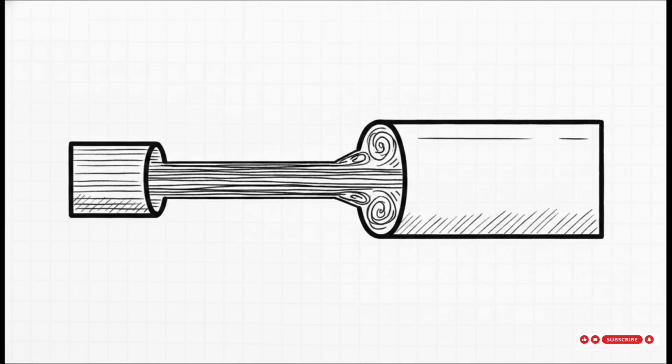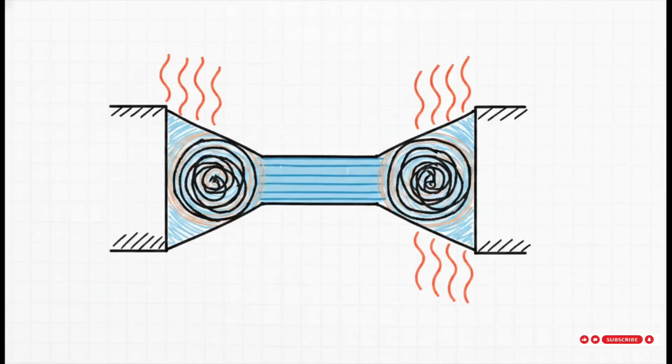If the pipe suddenly gets wider, the fluid stream actually detaches or separates from the wall completely and shoots into the larger space like a concentrated jet. Why do we care about this? Because that flow separation leaves an empty space between the expanding jet and the pipe wall, and nature hates a vacuum. That space instantly fills up with spinning fluid vortices, or eddies. These eddies cause a massive, completely irreversible conversion of your mechanical energy into heat. You are permanently draining pressure head from your system just because the pipe size changed too fast.